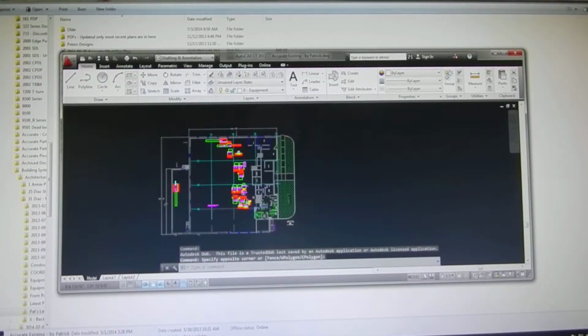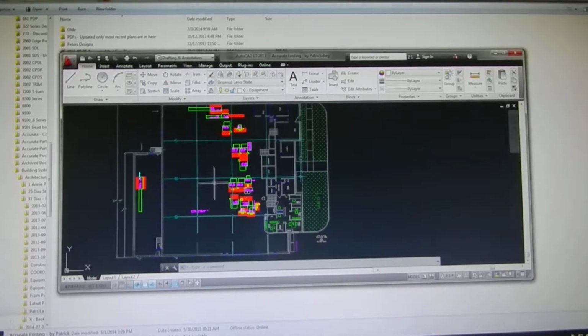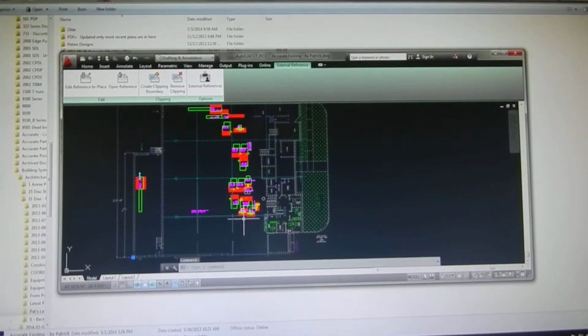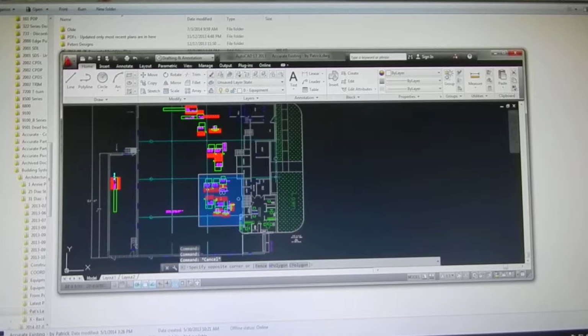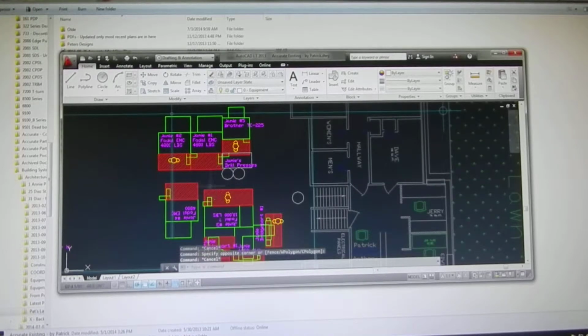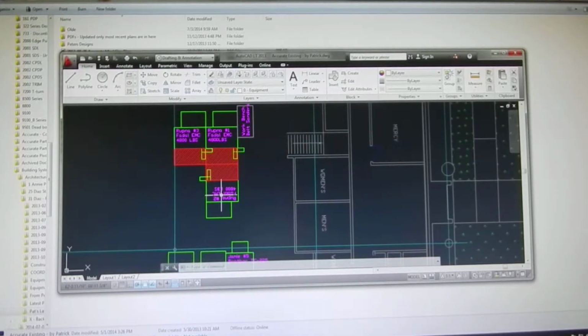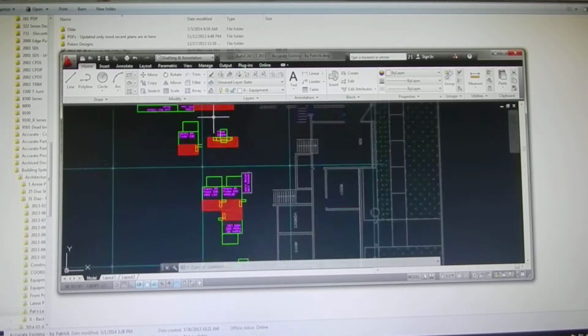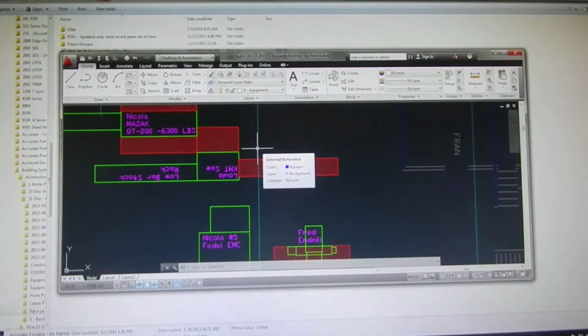it was laid out. So we had an architectural floor plan from the architect. We imported that, changed some layers, so you can see when I click on it, it's just an X-reference background. And here are different machining cells grouped together. Label them, call out the machine number. Important to have a schedule for each that lists every machine. Give its pertinent data, date purchased, electrical consumption, and ratings, and then you could use that schedule to create a